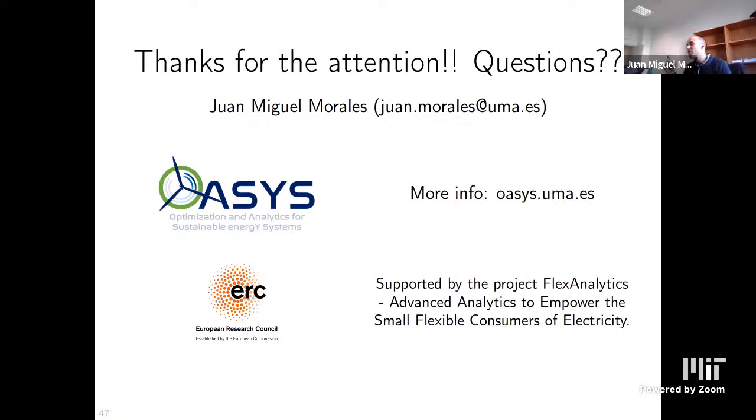Okay, this may have several answers. We don't account for spatial correlation within the ambiguity set. This is something that has been studied by other people like Adriano Arrigo, where they include a spatial correlation of the wind power forecast errors through copulas within the ambiguity set. If you are referring to how we generate the data, we do include the spatial correlations in the way we generate the data, but we don't construct an ambiguity set that knows something about the spatial correlation of the wind power forecast error.